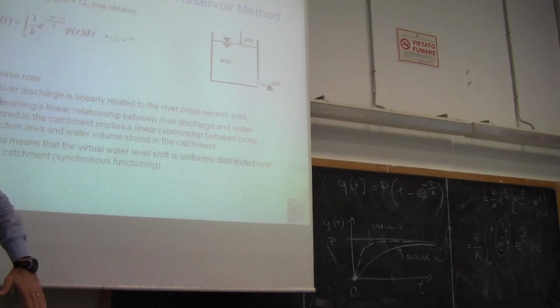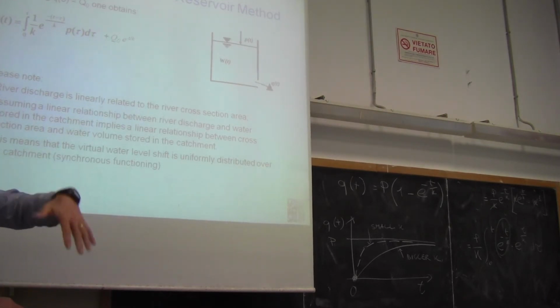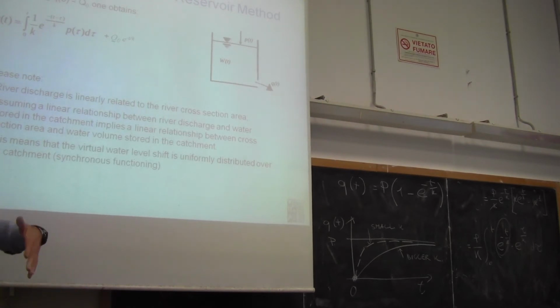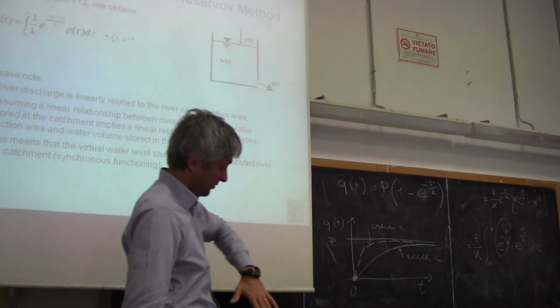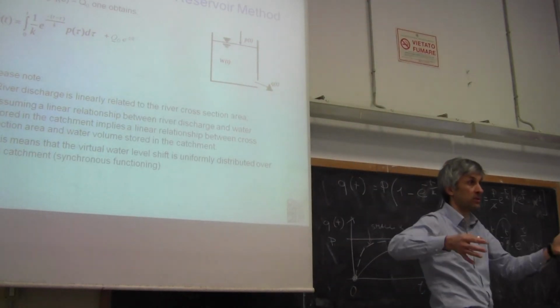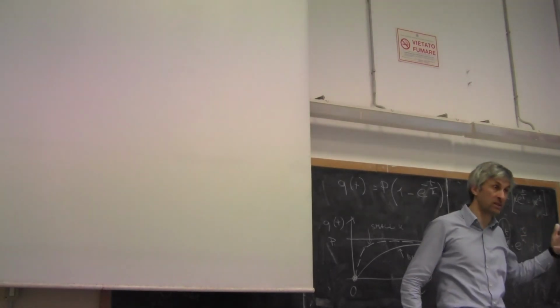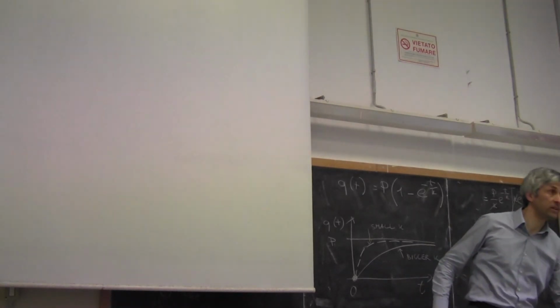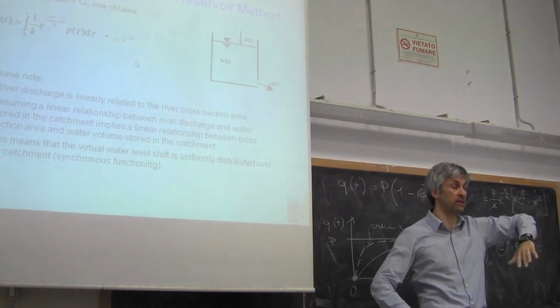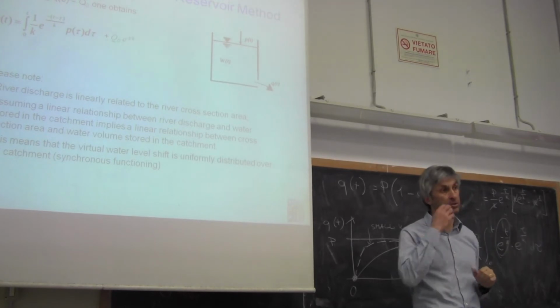If you have a steep catchment, water runs very quickly over it and doesn't have time to infiltrate, so infiltration is reduced. Also, if a catchment is steep, probably you will find rocks over the hill slope, not permeable soils, because if a soil is permeable, it's eroded in the long term, and the slope of the hill slopes decreases through erosion.